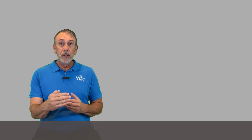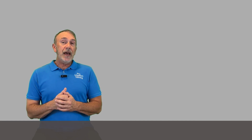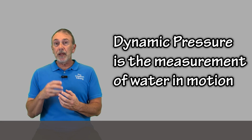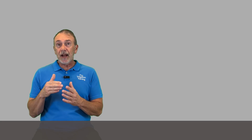Now let's talk about the definition of what pressure is. Pressure is the potential to push the water through the pipes, right? It's an energy potential, and you have two different ways of measuring it. You have static pressure and you have dynamic pressure. Static pressure is the water not moving, right? You've got water up to your irrigation system, and we can put a gauge on it and measure what it is as it's sitting there under pressure but not moving, right?